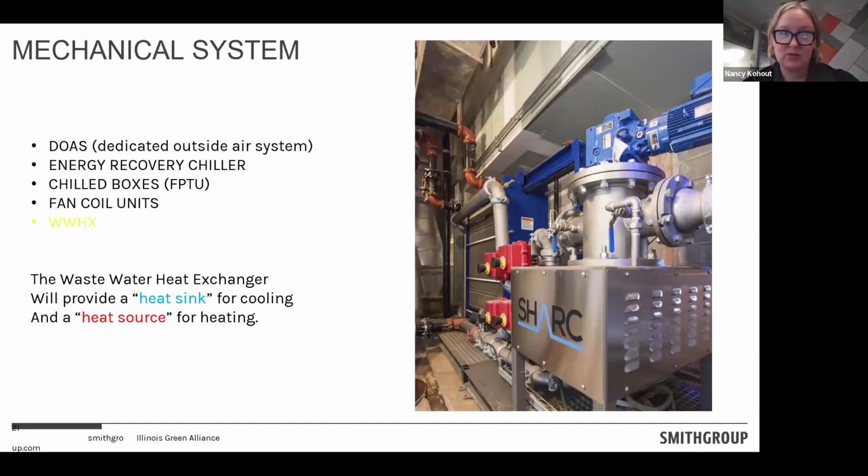Chilled boxes, which are sort of a chilled beam type system with a fan, and they typically don't have latent cooling, so they don't have condensate drains and wet coils and stuff like that in them. They do the sensible cooling, or like sort of the dry part of the cooling. Fan coil units as well. And then this wastewater heat exchanger, which is what I'm really telling you about today.